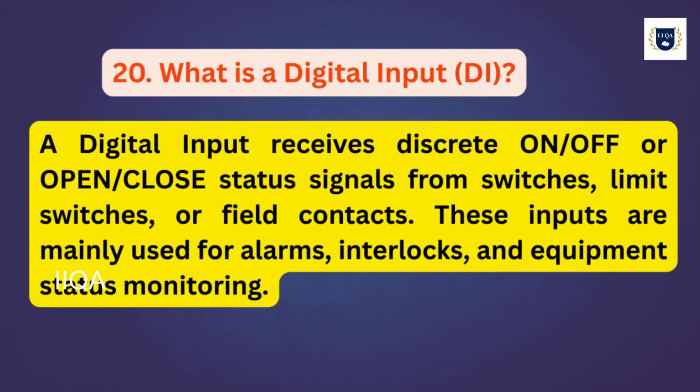What is a digital input, DI? A digital input receives discrete on-off or open-close status signals from switches, limit switches, or field contacts. These inputs are mainly used for alarms, interlocks, and equipment status monitoring.